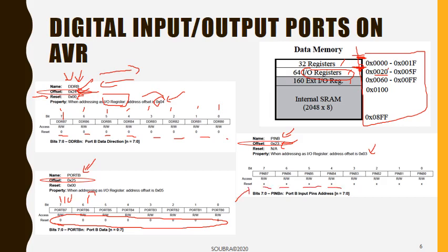And you should know that because you've taken the DSD course and I've talked about it there. So x is not a don't care, it's more an unknown. How come? Well, remember, PINB is the register where you read the incoming data. So here you can never know what kind of data your sensor, let's say, will be spitting out to your microcontroller. So you cannot fix it because it could be anything driven by the sensor. Hence, it's unknown.